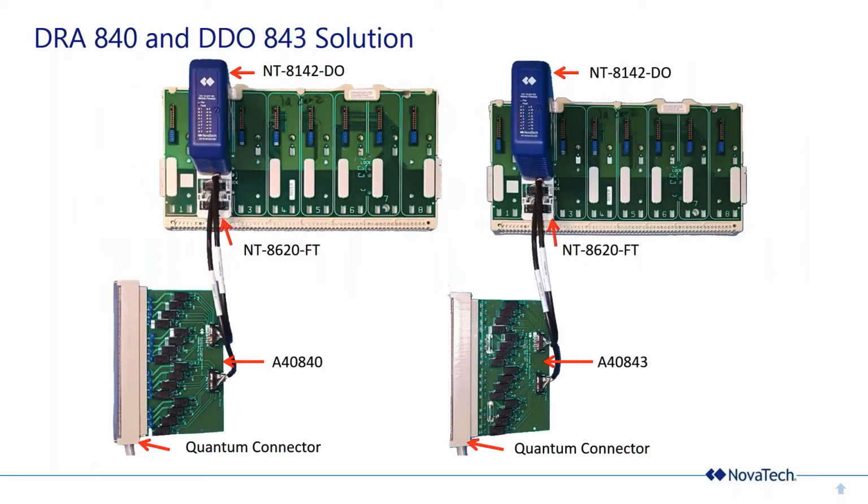What it basically looks like is this, a kind of photo picture diagram of it. So we have the quantum edge connector down here with the field wiring connected to it. Well, the field wiring is either directly connected to it or it's coming through terminal blocks. We have a transition card that the edge connector is connected to. The transition card is connected in the factory with cables to 8000 I/O that corresponds to the I/O being replaced.